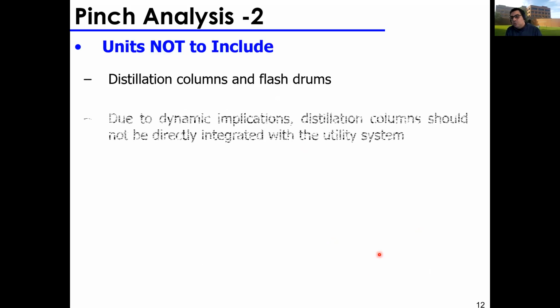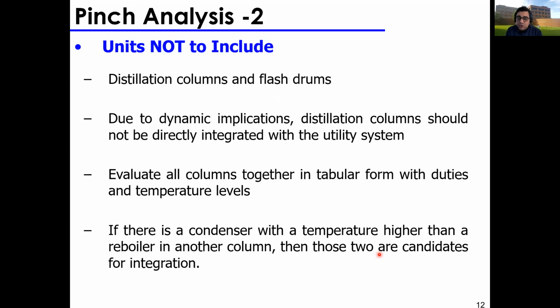Okay, what you should not include at the very first stage in your heat integration analysis is distillation columns, or when determining pinch points at the very first pass. Okay, so when looking at the streams, just ignore all the streams around the distillation column and look at all the other streams. Okay, if you're comfortable, or if there's a huge energetic gradient or a huge energetic jump, you can always do it. However, distillation column design,